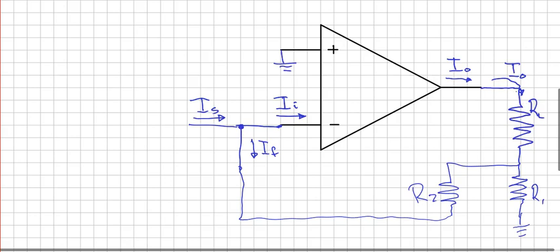In our case, we're trying to measure the output current here, and our circuit right down here, this one with R1 and R2, has the same current as I_out flowing in it, and the part going through R2 is turned into actually minus I_F. If you notice here, the current going this direction right here to the left is minus I_F.